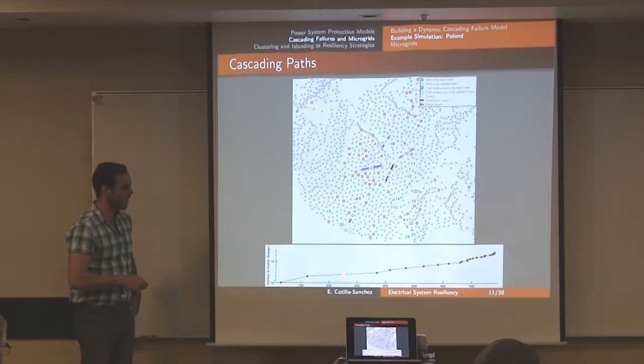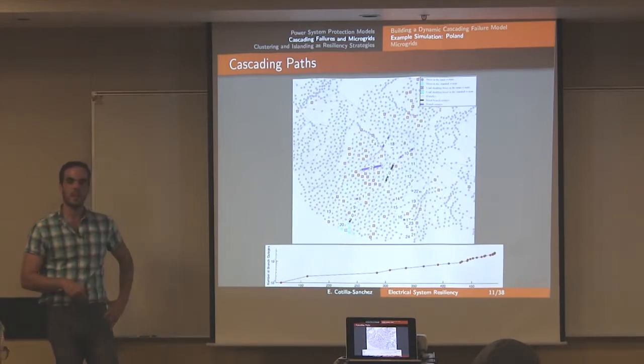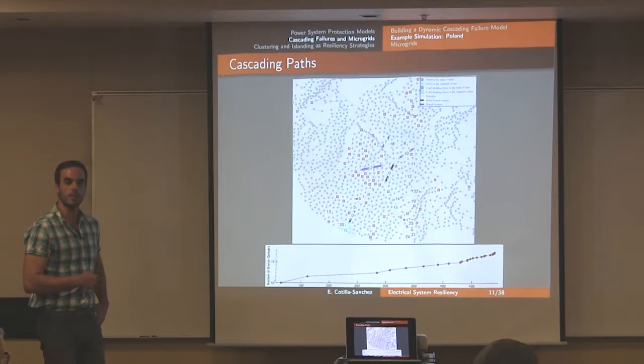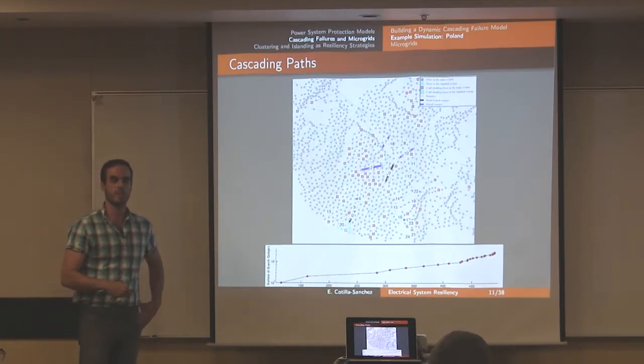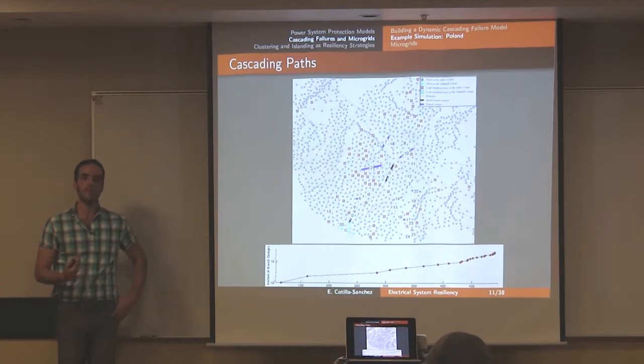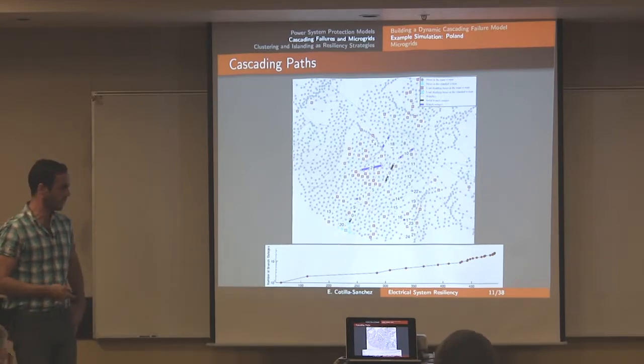So really having that timeline, this is seconds, so this is 150 seconds, 200 seconds. You can see how these are just the branches that are coming out. At the beginning, they're happening basically 100 seconds apart. This is a slow regime of cascading. If you look at the timeline of many of the events that have happened in large events, there's a very good agreement between the first stages of cascading, giving you this timeline, and then the later stages of cascading, giving you basically a few seconds in between them. So getting that information just from the analysis is very important to see before you can even think of any actions. This is basically giving you a budget of where to invest that time. So those two aspects for any kind of simulation are very important.